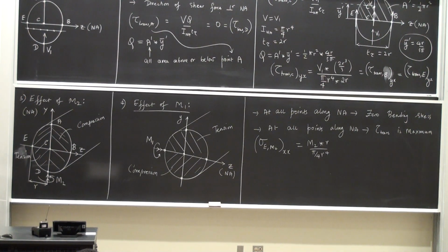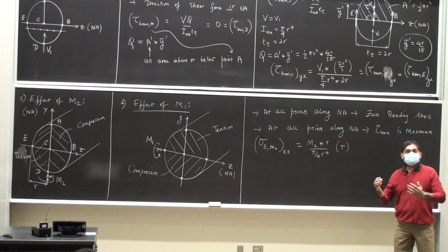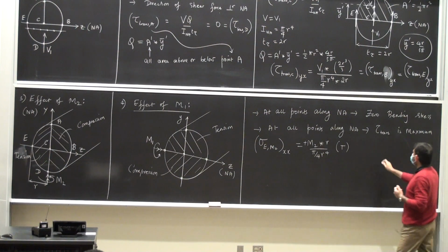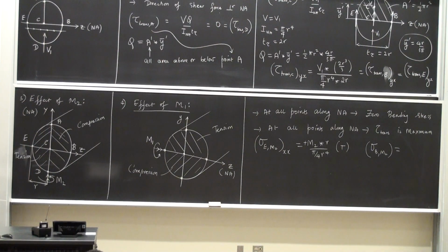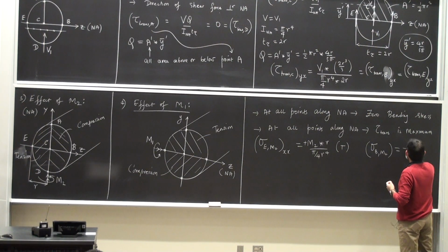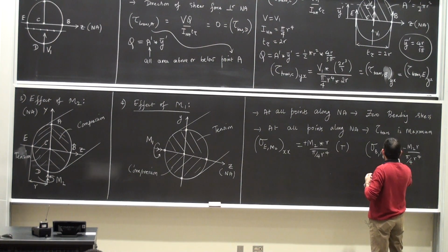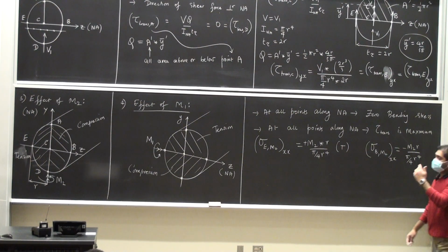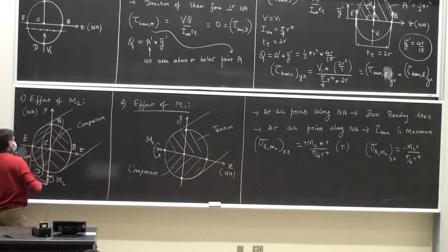Okay, so this is going to be in a state of tension. Typically, if you have a tensile bending stress, you write it as a positive sign. Then sigma B due to M2 is going to be compressive but at the same value. So minus M2 r over pi by 4 r to the power 4. And this is also along the x-axis direction. And at any other point, the bending stress is 0. So all of these points have 0 bending stress.